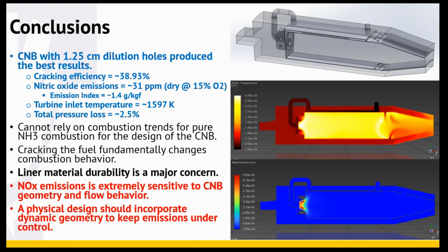So the final thing I'll say is that I believe with this combustor, one extra complication that will most likely have to be made is that the geometry is going to have to adapt. There might have to be some kind of NOx measurement tool implemented, or CFD simulation is going to have to be done at different points at takeoff, to figure out how you can tweak the geometry to best meet each point in the flight.